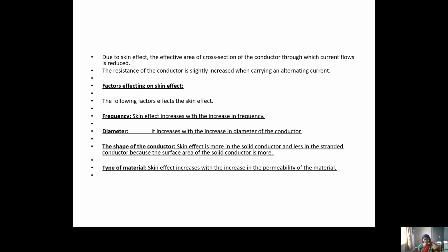Skin effect value will be more in the solid conductor, but it is less in the stranded conductor because the surface area of the solid conductor is more. Whenever the surface area is more, the skin effect will also be more. That's why in solid conductors the skin effect is more compared to stranded conductors. Type of material: skin effect increases with increasing permeability of the material. Different materials have different permeabilities, so whenever the permeability value increases, the skin effect will also increase.